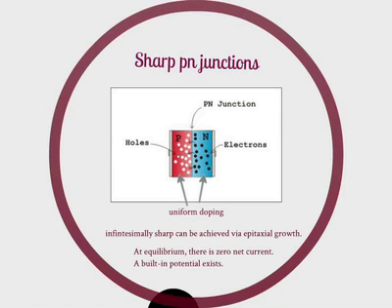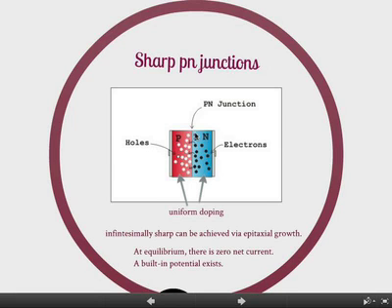That's it. They're locally done. And you do this with lithography. Essentially, you can pattern these areas and so on. And doping is typically done by what's called ion implantation, or you can do chemical doping. We talked about a few of these early on, but there are lots of different ways we can do it. So if you're interested, make sure you read that. But if it's important for understanding, I'll point it out. So for us, we'll just think about this as a cartoon picture. Okay? First, we will make the assumption that it's a sharp PN junction. In other words, it's an infinitesimal change. So you have a P-type material shown in red, with a very sharp boundary here, and then you have an N-type material.